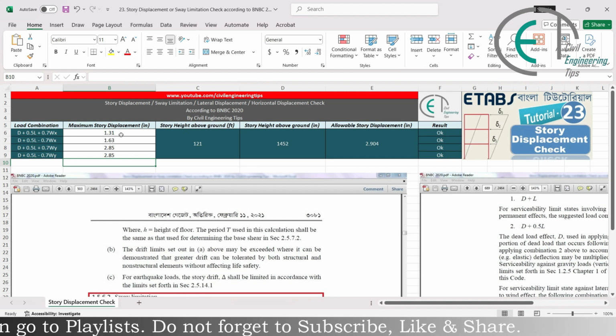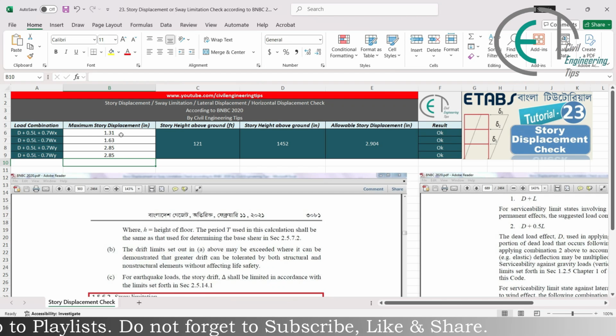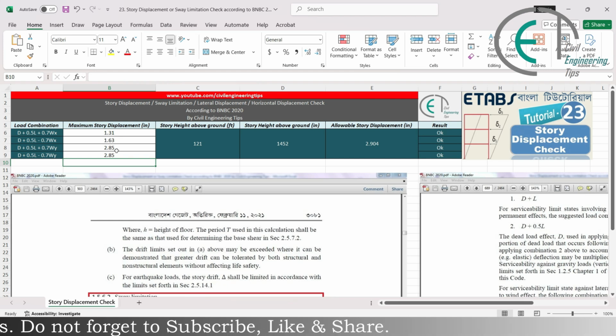There was not enough resistance or stiffness along Y direction, and we used 6 number of shear wall along Y direction and the displacement value decreases. So from this video we got the result that using shear wall is a solution to resist lateral force like earthquake or wind. It was a very useful and practical application of shear wall inside the building, and each structural design engineer should know about this fact.